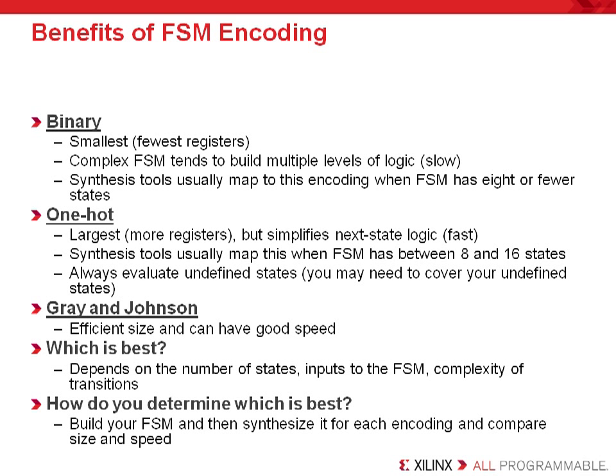The benefits of controlling the encoding of your finite state machine are mainly size and speed, but it is interesting to note that years ago most FPGA customers came to be concerned about their encoding because of design reliability issues. That is, 10 plus years ago, many customers were just not used to employing synchronous design techniques in their FPGA design. This was mainly due to ASIC design conversion, but in the end their design had to be synchronous to operate. Still, many customers had problems with their designs operating, and this would usually show itself with the finite state machine glitching. This was because most designers used binary encoding, and when a design glitches, it would usually cause the binary encoded machine to expose the flaw.